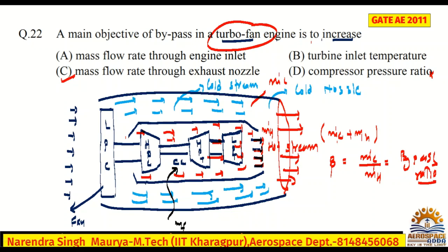So still here also there is a problem, but compared to turboprop, this problem is less. They will not get aerodynamic installation problems early. But in turboprop, early separation of the flow or aerodynamic stalling you can get on the propeller blades. So that is the difference.